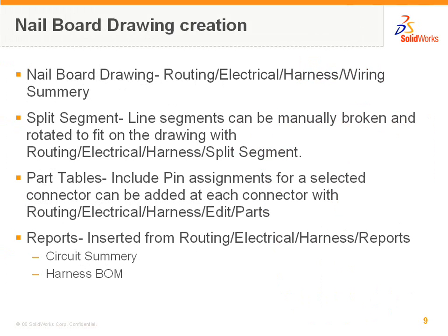Nailboard drawing creation. The nailboard drawing is essentially a schematic of our electrical route. In order to generate a nailboard drawing, from the pull down, routing, electrical, harness, wiring summary.